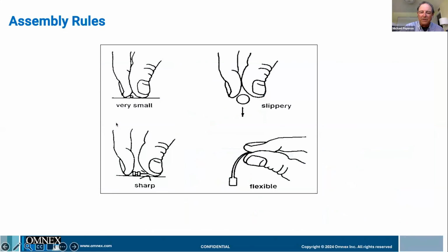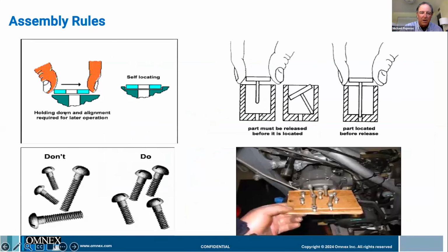Right? There's a lot of design opportunities in geometries and in size of things. Flexibility, shape, right? Just kind of gross examples there. Here's self-locating. Give me some kind of alignment to help put a washer onto a hole. Give me the right length of a pin going into some bore, right? So I can actually have positive feedback that I made it.